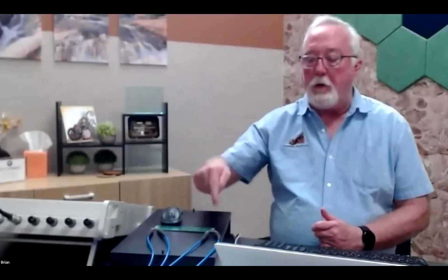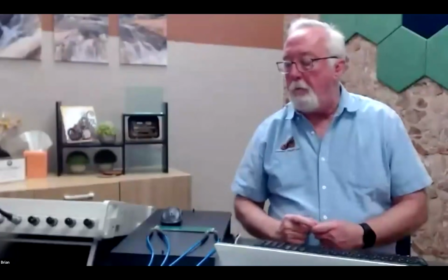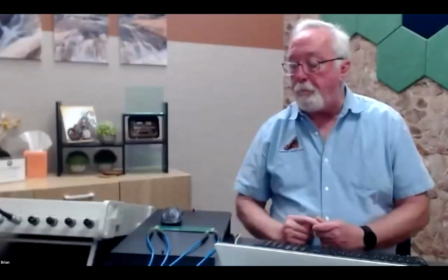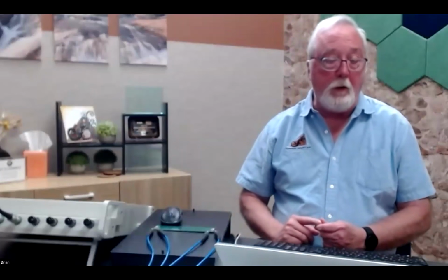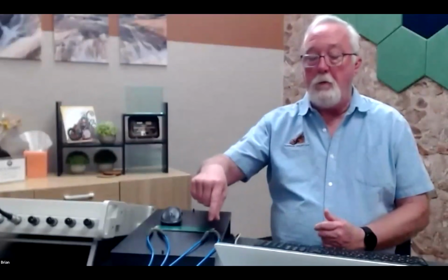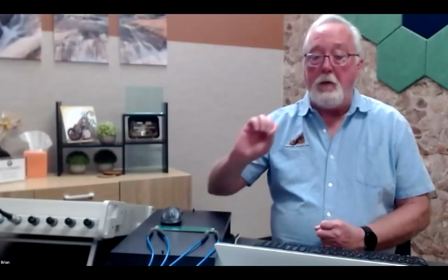I can't have it open because I actually had it soldered to the board. But it makes a single-sided measurement, generates the 2-port S parameters for the pigtail, and then I use that for de-embedding.